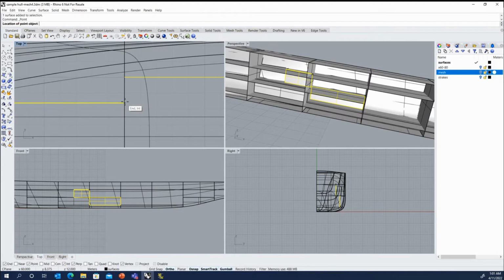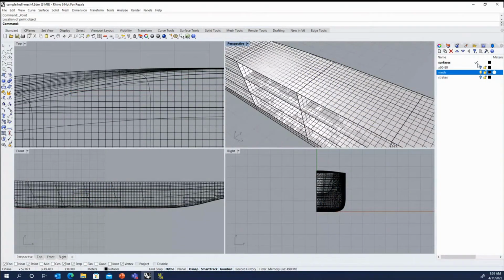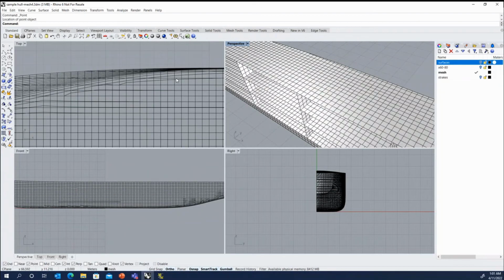So depending on what the structural drawings call for, we're going to want to create nodes at every location where we have a stiffener. So we're going to assume that our structural drawing for the deck says there is a stiffener at 1 meter increments, and this bulkhead will land in between stiffeners. If you look at the mesh that was created previously, you can see it's not quite uniform spacing. If we were to, let me turn off the surfaces there. If we take a single point there, or if you want, under the Analyze menu, you have an option for length or distance.